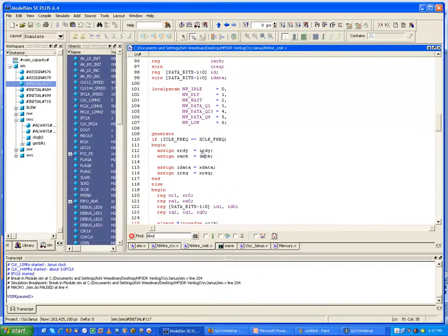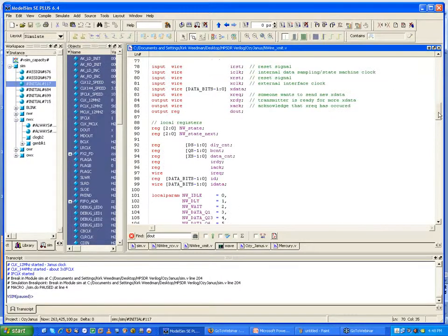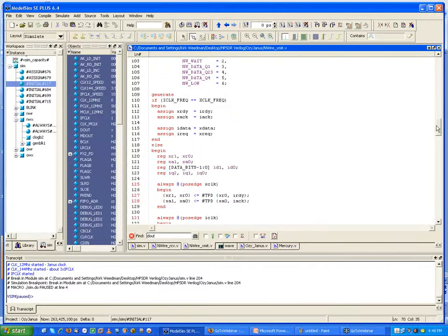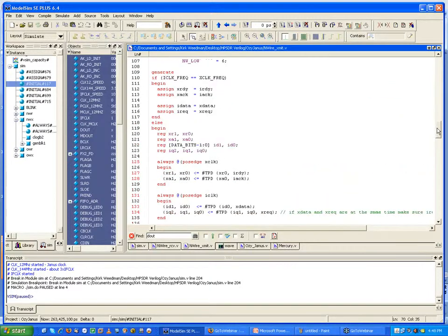And that's basically what I've done for these handshaking signals, such as I ready, I ack, data. I can directly assign the X data that's coming in, because X data is an input right here, an input into this module. So I can assign the X data to my internal I data. So it makes it very simple for this case where the clocks are the same.